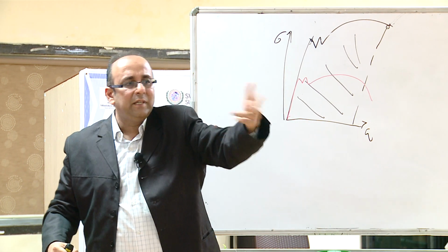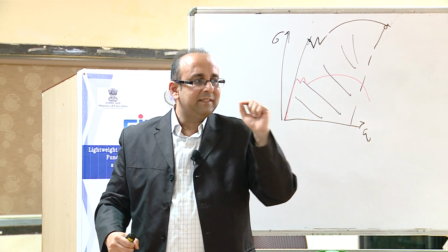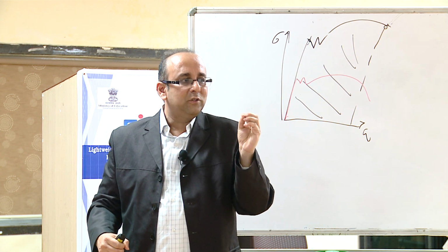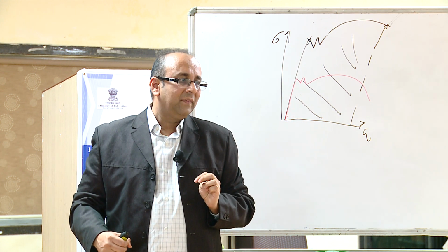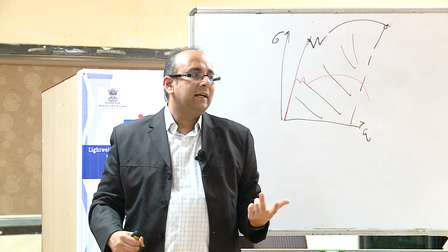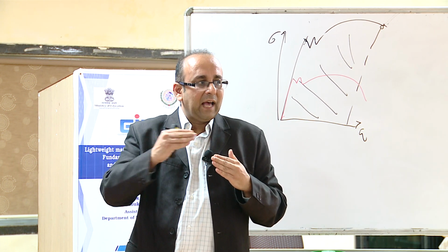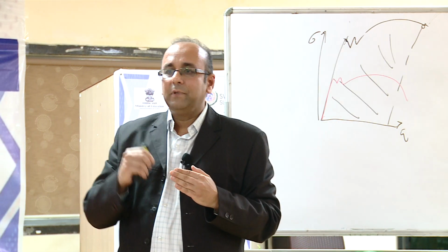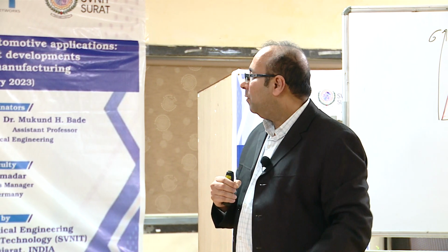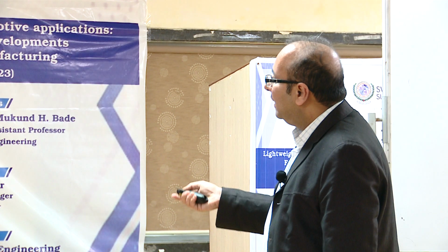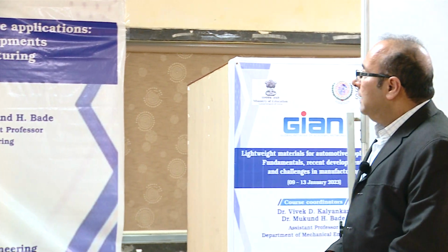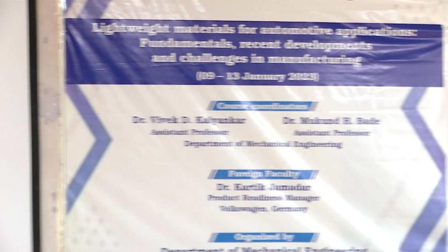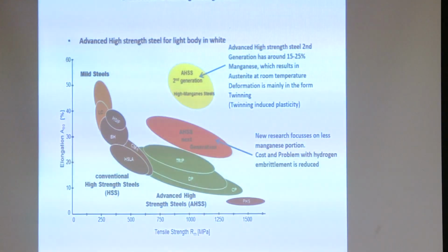When you have advantage, you have some disadvantage also. And the biggest disadvantage is the hydrogen inside this material. And hydrogen embrittlement happens, and eventually with time, this material starts getting cracks because of hydrogen embrittlement. The second problem, basically, is that this material has a very, very high spring back.